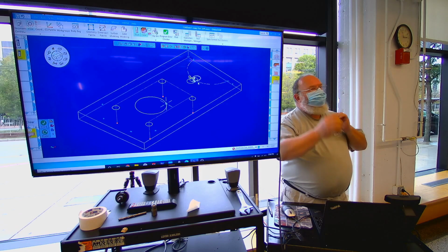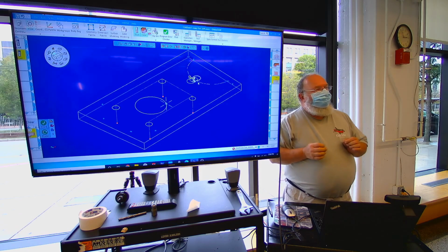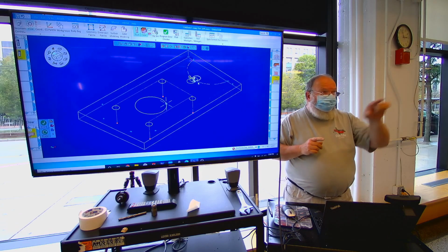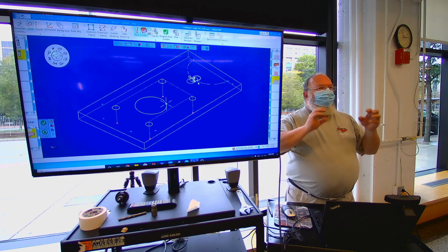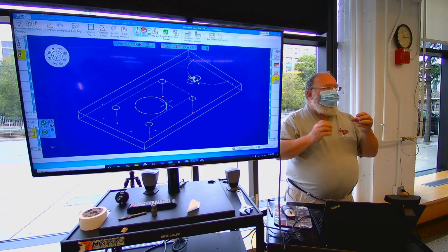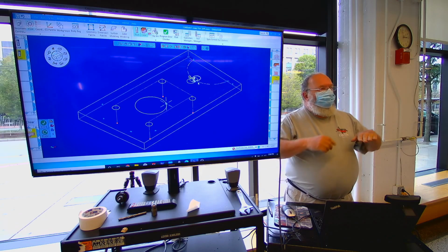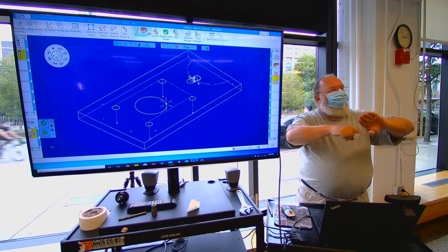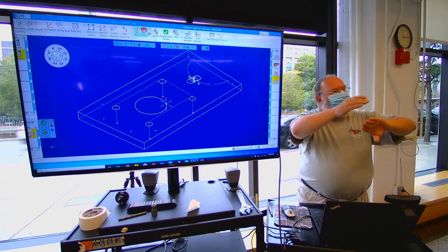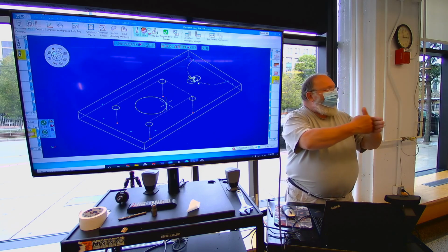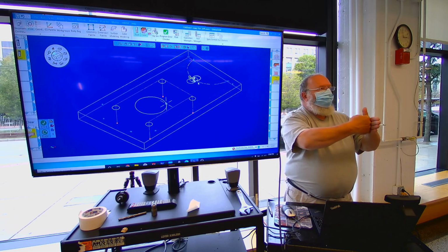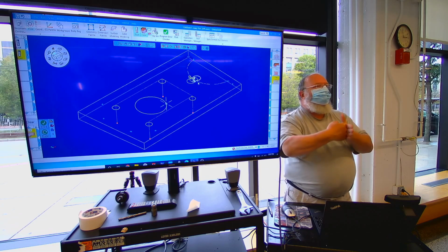The reason we still have the option of conventional milling is this is going back into history, when we had the manual machines, and we still have the problem in the manual machines. If you've ever put a nut on a bolt and pushed them back and forth without spinning, there's play there. It's called backlash. Well, in climb milling, if you look down on top of the tool, it's trying to climb its way around the geometry. But what it's also trying to do is pull the stock. So if I'm driving my workpiece this way and my tool is trying to pull it, what it's going to do is keep jumping it into that backlash.